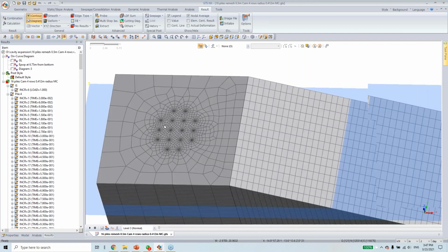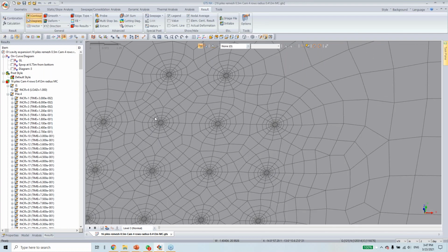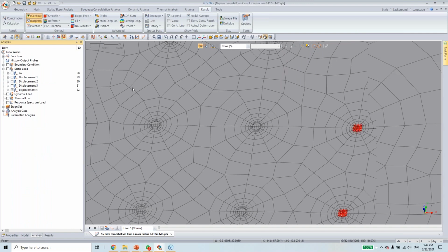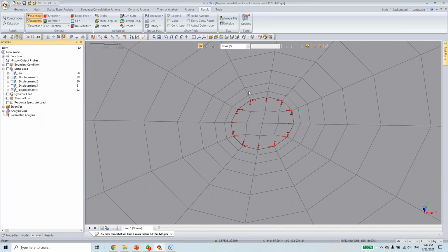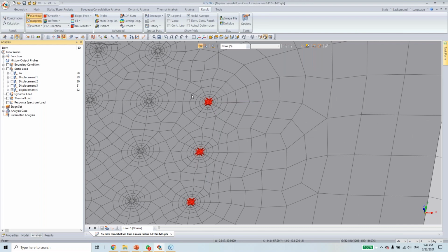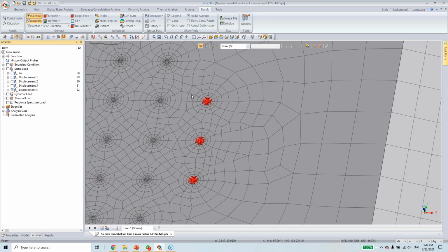And how we model the pile installation is by applying the radial displacement around the piles from radius of 0.1 to radius of 0.412. How we get the 0.412 is by calculating the equivalent area for 0.4 meter radius spun pile.